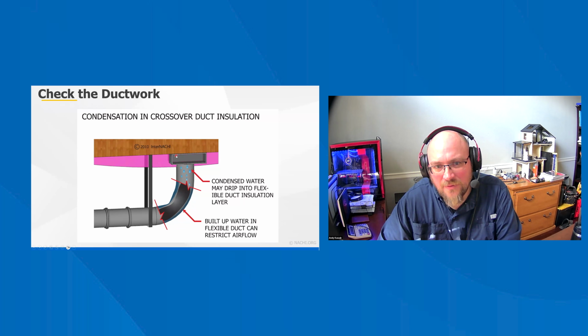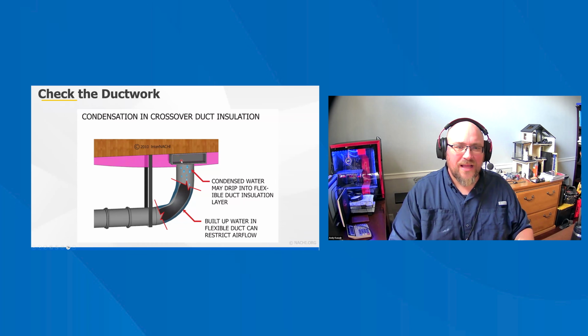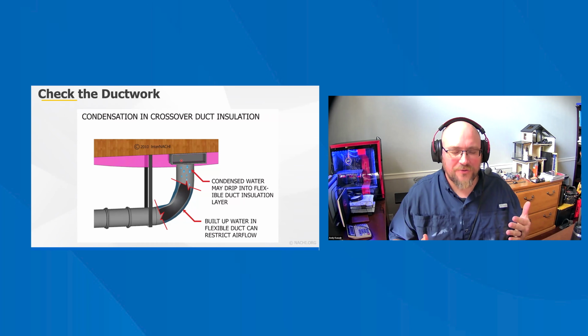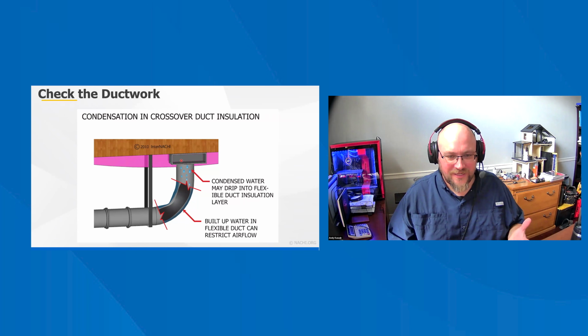The homeowner that was living in the home had no idea how to open and close their crawl space vents. Their vapor barrier or vapor retarder on the crawl space floor was not consistent. There were gaps all over the place. So we had really high humidity in that crawl space, and they didn't open their vents during the summertime.